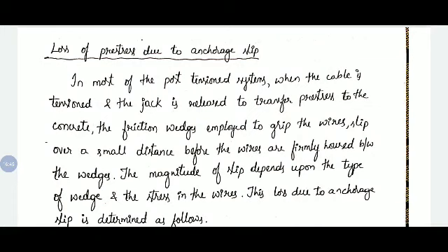So in that case, after applying the tensile stress, you are going to hold the tendon in the position by using anchorage devices. So one side it will be fixed, and from another side you are going to stretch the tendons. After applying the required pre-stressing force from one side by using jacking devices, you need to fix that tendon with same stress. So for that we are going to use the arrangements called anchorage devices.